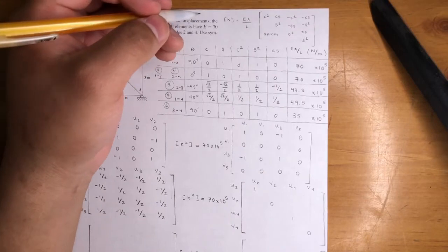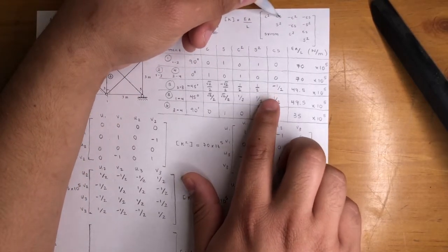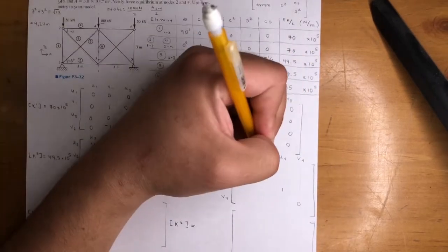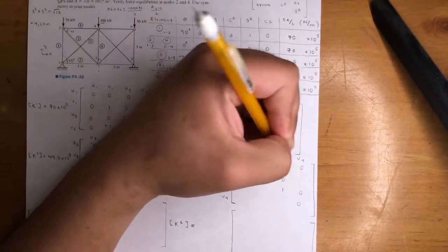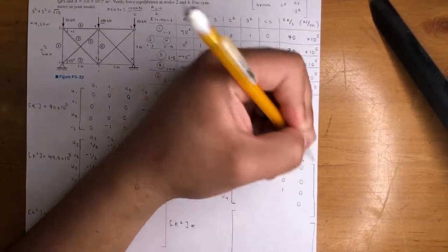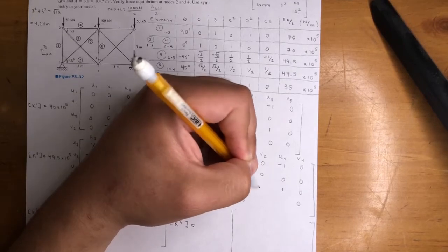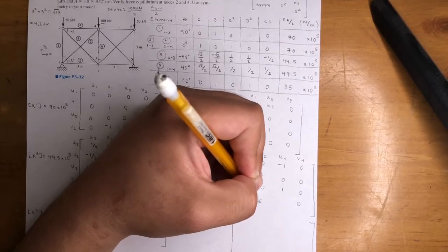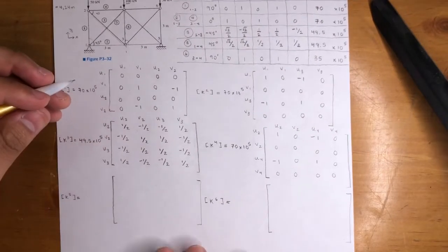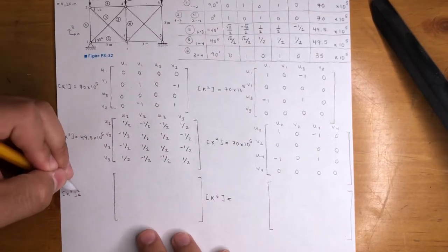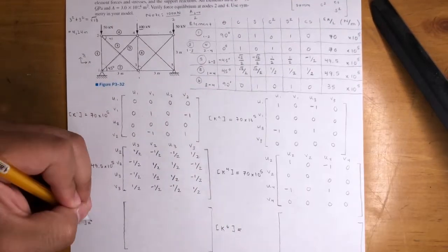And then we're going to plug in, what is this? CS. So it's, oh, right here, 0. So it's 0, 0, and 0. And 0 up here. That's going to be a -1 and 0. So 0, -1, 0. After a while, you just know the tricks, right? It's too many problems. You'll get the hang of it. K5. Element 5, that is 49.5 times 10 to the 5th.